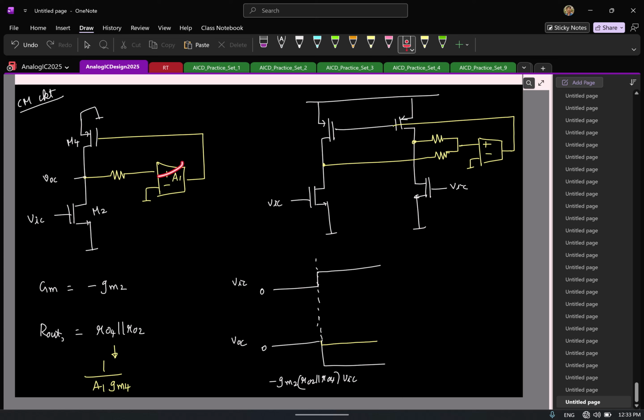And ideally you want to have a really large gain here, so that the output common mode is defined to the required value. Right? This is not grounded. This is connected to some VCM ref. So which means now it seems like even in a pseudo differential case, the moment I have a common mode feedback, the CMFB is helping me suppress any changes in my input common mode. Correct? Does it make sense? Earlier, one of the reasons I mentioned against pseudo differential was that it does respond to common mode inputs. Whereas now I see that if I have a CMFB, which is what you have to use, this jump is basically suppressed a lot.